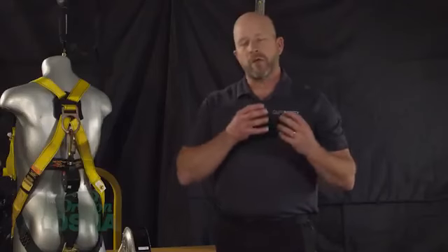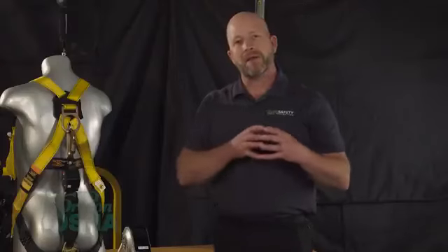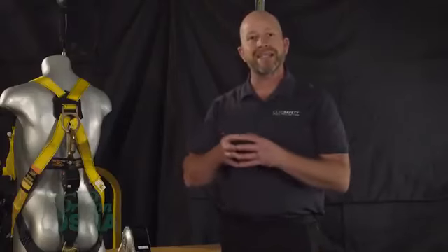One of the ways that you will absolutely know that a piece of equipment is or is not designed to be used in that configuration is, of course, to reference the manufacturer's instructions. They are going to be the ones that will dictate what edges it is acceptable to use on. However, ANSI, the ANSI committee that first instituted the leading edge testing requirements, also mandates that the manufacturers clearly identify with symbols a retractable that is or is not rated for leading edge.